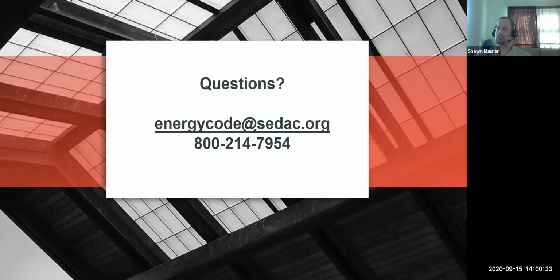Okay, our next question: if a basement is to be left unfinished, will it still require insulation on the exterior walls? This depends whether the basement is conditioned or not. If you insulate the floor above the basement, and that basement area is thermally isolated from the house, it's got a weather-stripped door down the basement stairs, the floor is insulated, then no, you do not need to insulate that basement wall. But if that basement is conditioned, if like your air handler is down there and you've got supply and return vents, then yes, even if it's unfinished, it will need to be insulated.